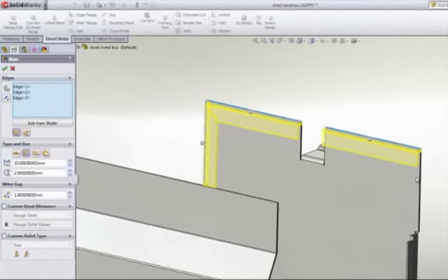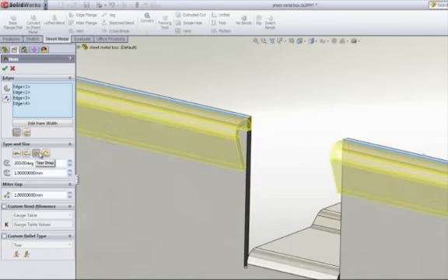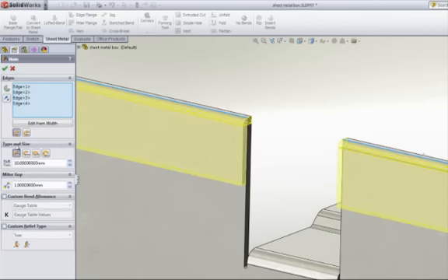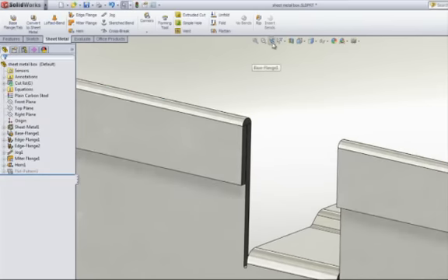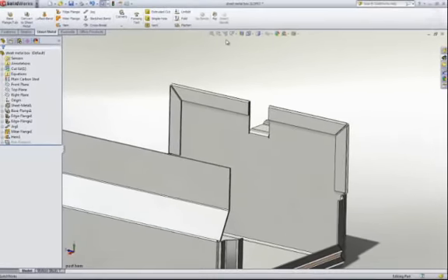If you need to reinforce an edge or remove sharp edges, then you're going to need to add hems. Hem types, such as open, teardrop, rolled, and closed, should cover all your requirements. Of course, sheet metal design is not all about creating bends. Ventilation holes, mounting features, and strengthening ribs all play a part in the final design, so these should be simple and fast to create.